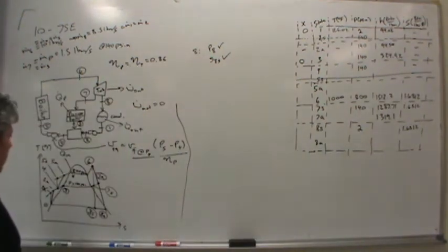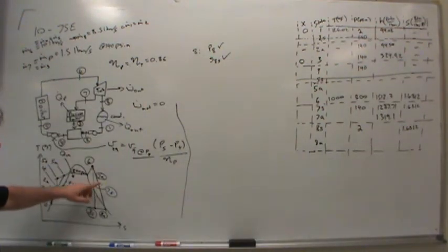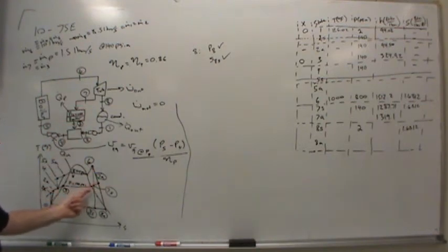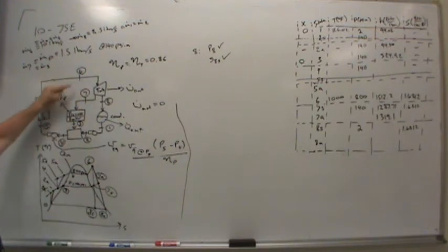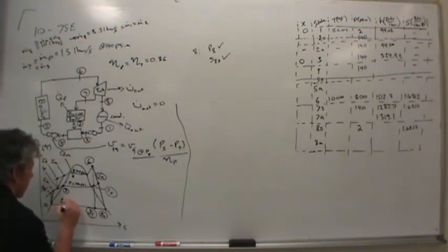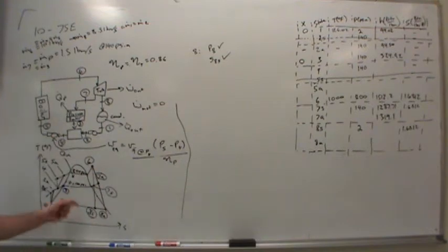Why not? Well, just like with state 7, I may have written P7S, but I didn't mean to do that. The pressure is the same no matter what. The pressure coming out of state 7 has to be 140 psia. So we've got to do whatever we can to make that the case. That's why this is just one pressure line for 140 psia. Similarly, the condenser pressure, which was what, 2 psia? The condenser pressure is the same regardless of whether it's state 8A or state 8S. Now, I imagine that 8S is going to end up in the saturation region, but let's find out.